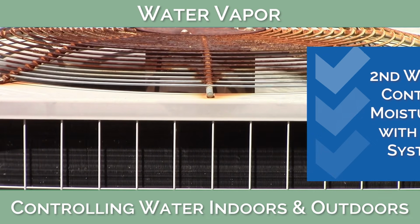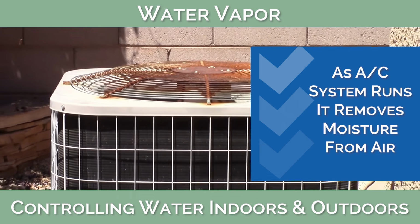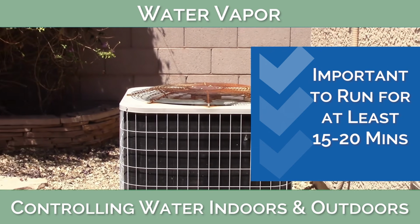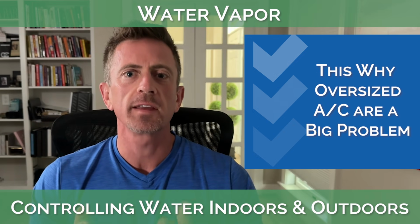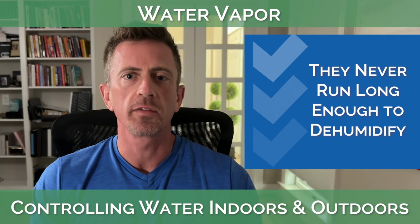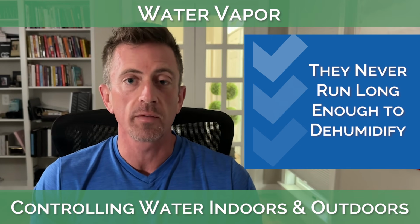The secondary way you control moisture indoors is with your AC system. As the AC system runs, it removes moisture from the air. So it's important that your AC system runs for at least 20 minutes before shutting off in order to dehumidify the air properly. This is why oversized AC systems are such a problem in humid climates. They never run long enough to dehumidify the air, which leaves the indoor air cold, clammy, and uncomfortable.